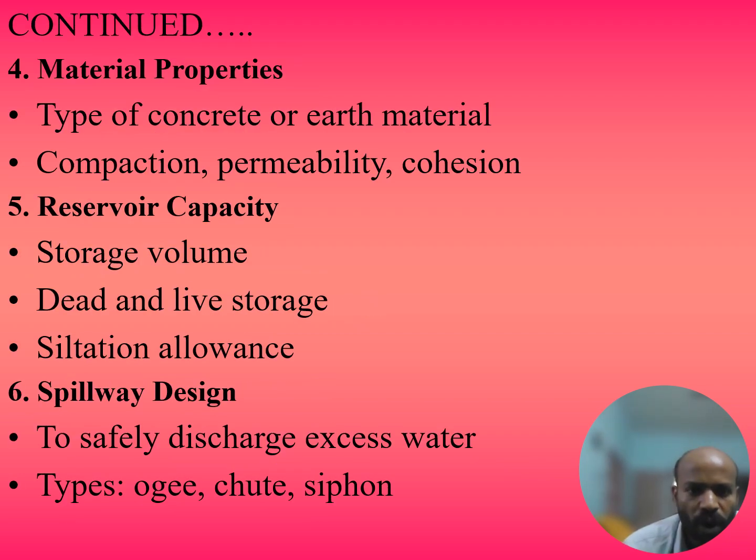Next, material properties. Material properties mean what material the dam is made of, and the compaction, permeability, and cohesion are the important properties of underlying soil. Reservoir capacity, importance is given here to storage volume, dead and live storage, and filtration allowance.